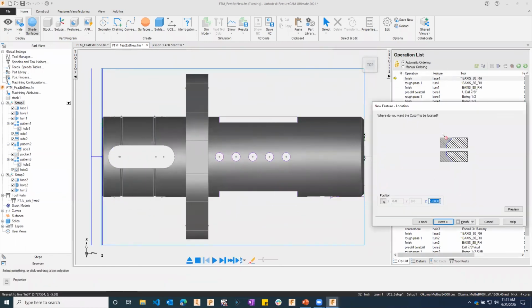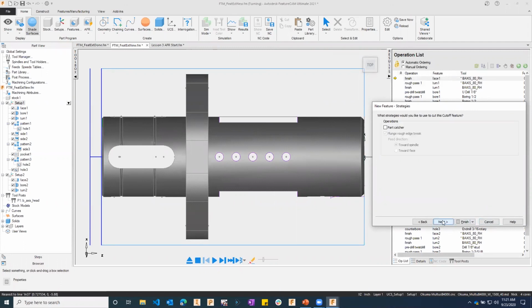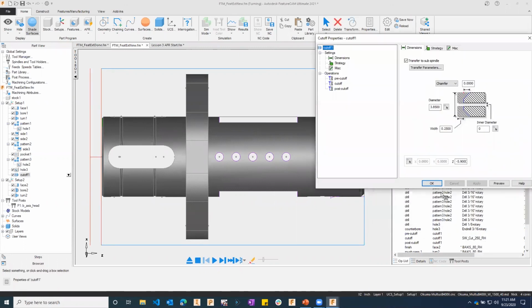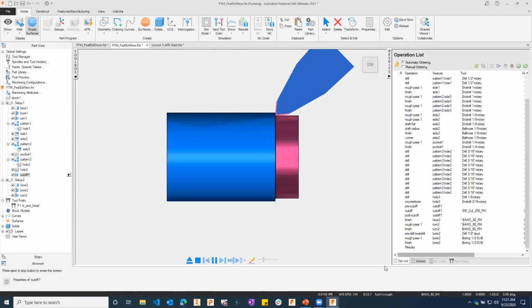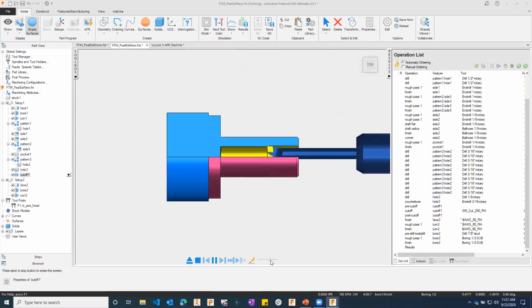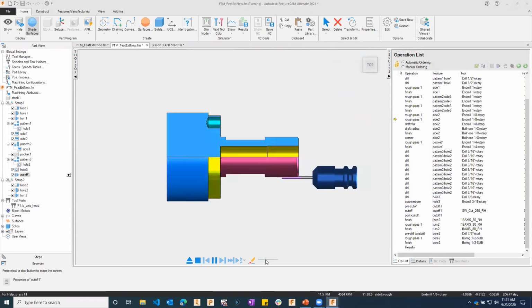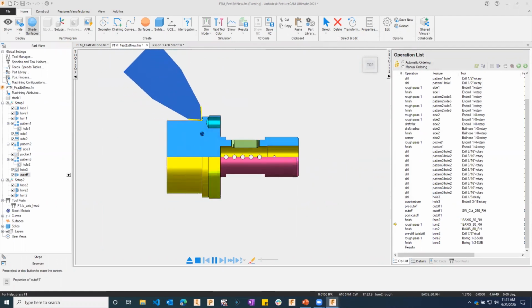And I might even go a little bit past there just to leave some room to face off and give a real nice surface finish on the backside. And say, okay. And that should do it for this part. So we do all setup 1. It parts it off, transfers to the sub-spindle, then we come back on the other side with our B-axis.